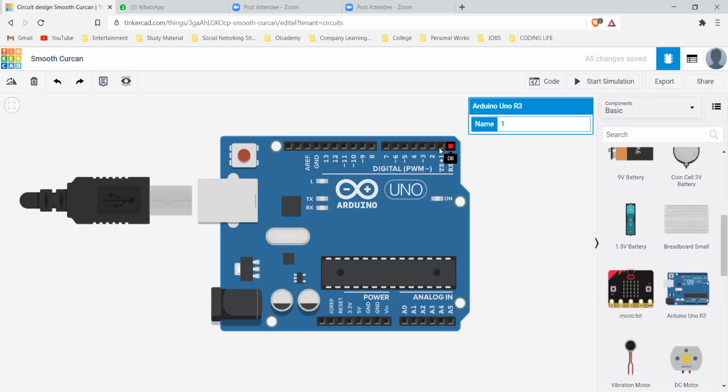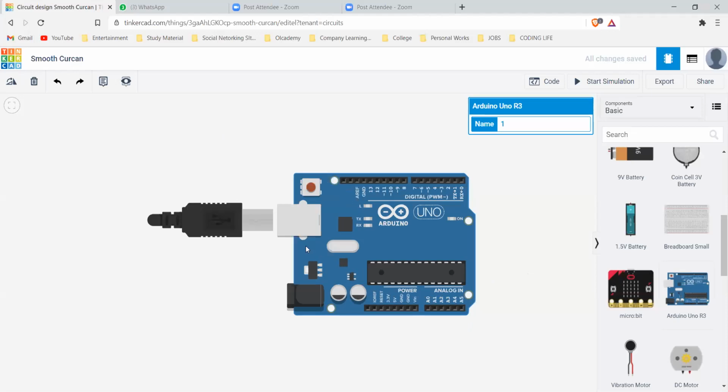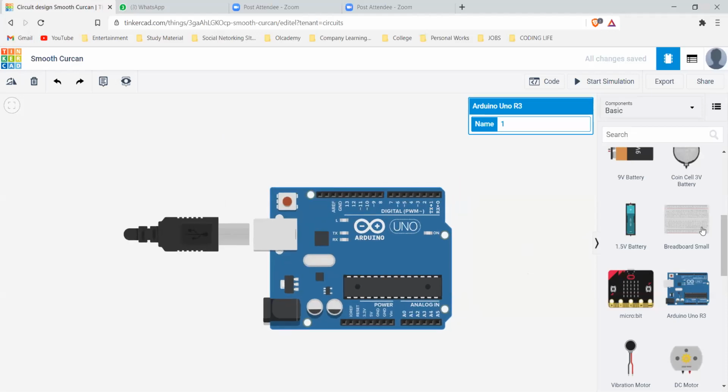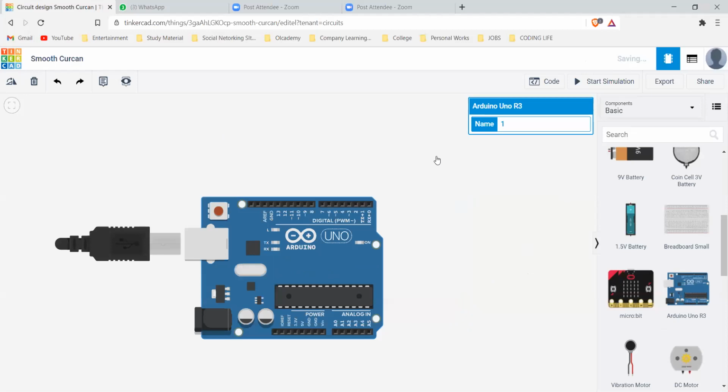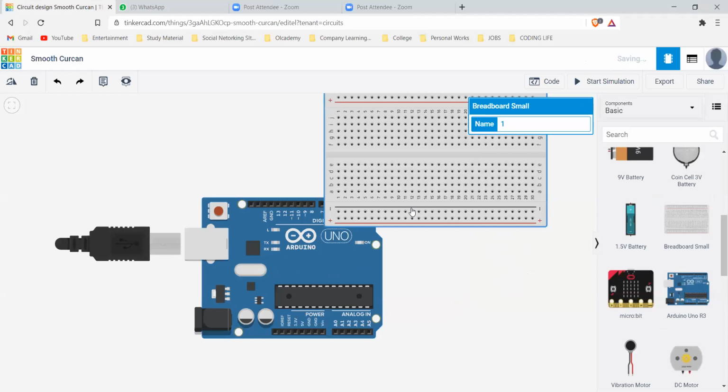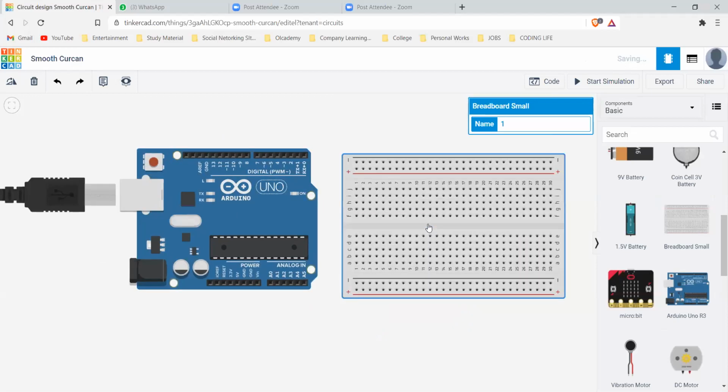So let's see the basic example. Okay. So what if you want to start an LED using an Arduino? Let's take a breadboard for better understanding. Sometimes what happens is we usually do not know how the breadboard is connected in the back. What TinkerCad does is it also helps you to know which point in the breadboard is connected to what point.